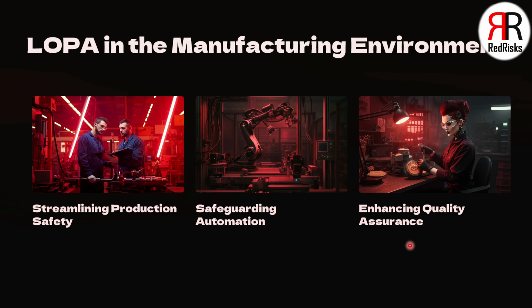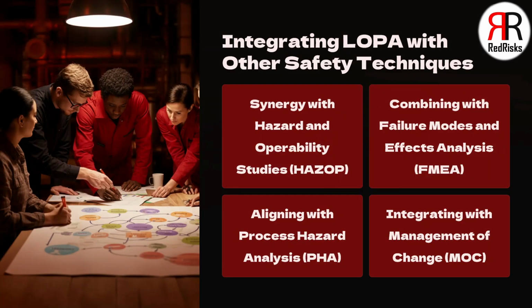Let's consider looking at integrating LOPA with other safety techniques. LOPA really complements HAZOPs by providing a more quantitative approach to assessing the effectiveness of safeguards and determining the required safety integrity level, the SIL. In terms of FMEA, failure modes and effects analysis, FMEA identifies potential failure modes, whilst LOPA evaluates the likelihood and consequence of these failures, enabling a comprehensive safety assessment.